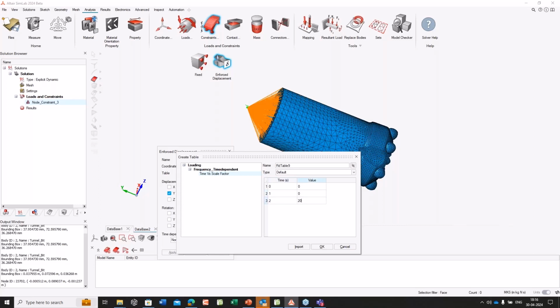the geometry by 20 mm as a forward motion. And then in the next second I want to bring the model 5 mm back, so that is a 15 mm position. Similarly you can increase by 20 mm, which is 35 mm, and then bring it 5 mm back, which is 30 millimeters, and then add another 20 mm in the forward direction, so 30 plus 20, which is 50 mm. This is how you can define the motion.